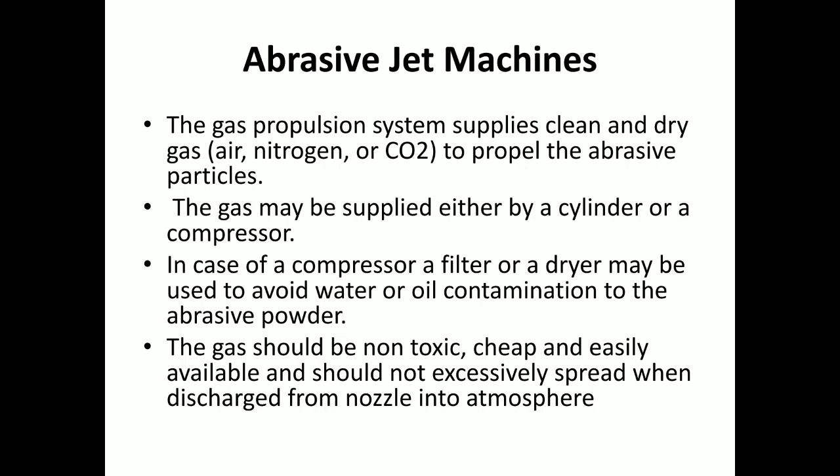This should be kept in mind. The gas which you are using should be environment friendly, non-toxic, cheap and easily available, and should not spread excessively when discharged from a nozzle into the atmosphere. If it spreads, the shape or contour which you require will not be attained, because the contour will be more widened.